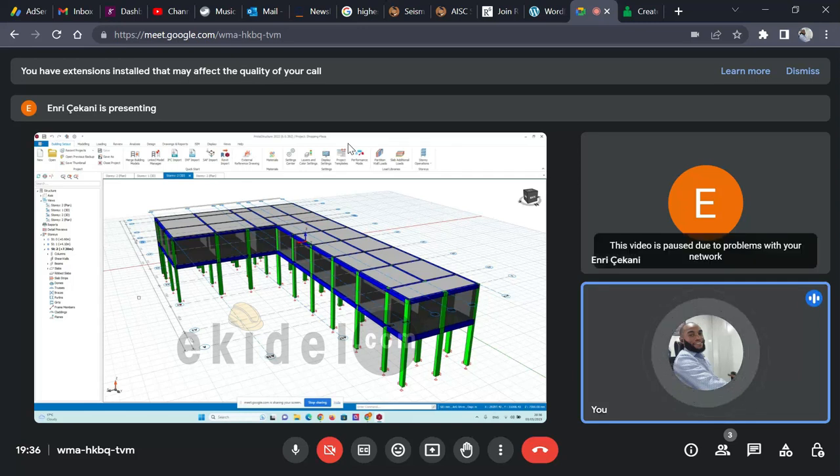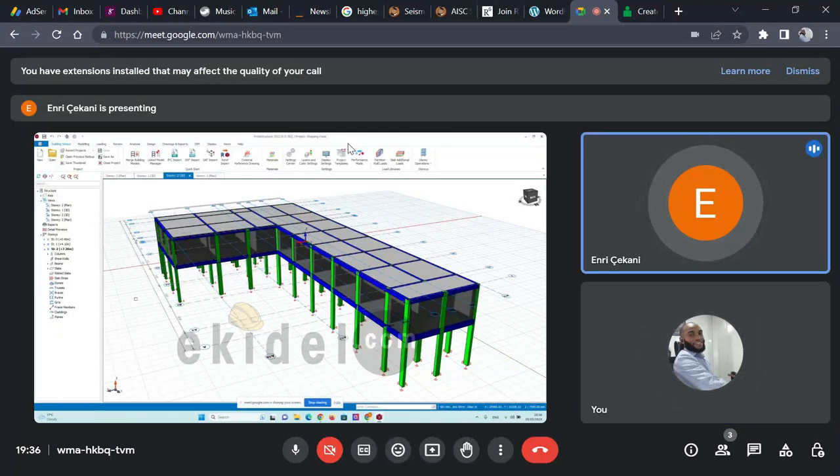Also, bi-diagonal reinforcement is very useful for shear resistance, since it was seen that normal links, the conventional links we use for beams, are just not useful when it comes to earthquakes. But if you introduce bi-diagonal reinforcement, it will be able to control uplift or shear failure. This is only for high ductility structures.